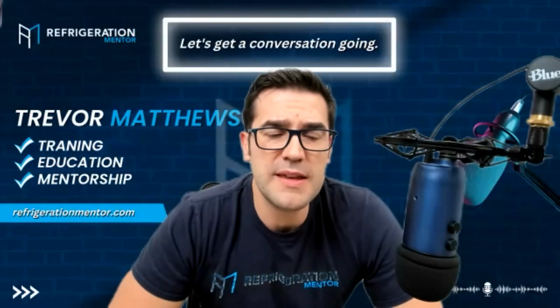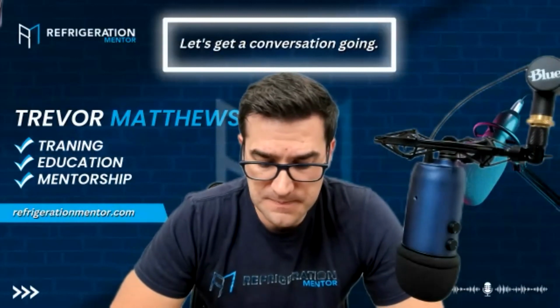What is another type of mechanical failure that you'd see there? Well, I would probably consider floodback to be the next one that's a concern. And floodback doesn't necessarily mean slugging in refrigerant-cooled applications, right, but it does lead to what's called oil dilution. Slugging and floodback, when I went to school and the apprentice program, they kind of laid that in as an immediate problem and immediate death. And that's not necessarily the case.